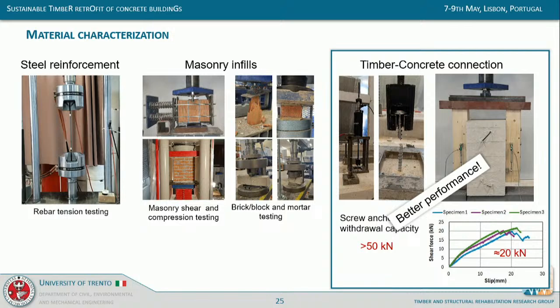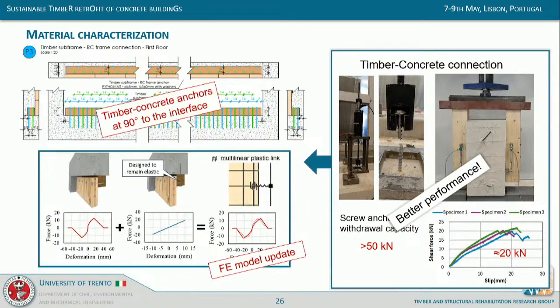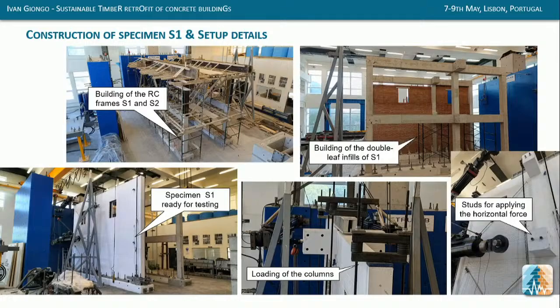So that is strong enough so that we could prescribe a different application. So 90 degrees, so easier to apply, something that is doable actually on site. But then it means that when moving them from axially loaded to laterally loaded only, we had to take into account the deformability, which wasn't included before, so we had to update the model. And of course, we updated the curves that I'm not showing you yet.